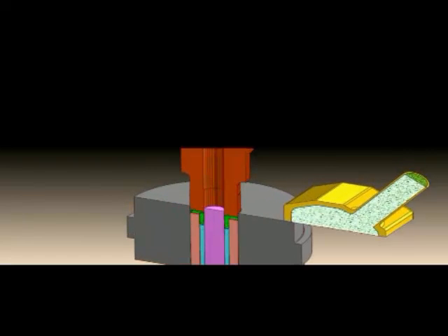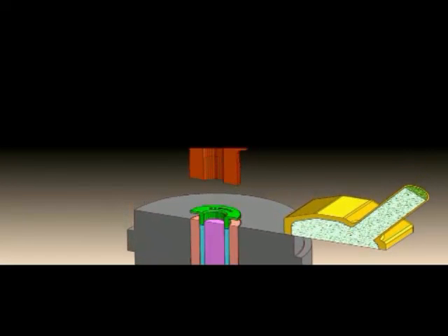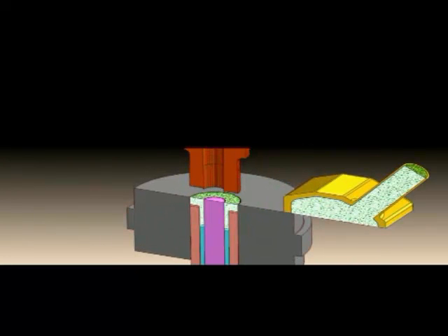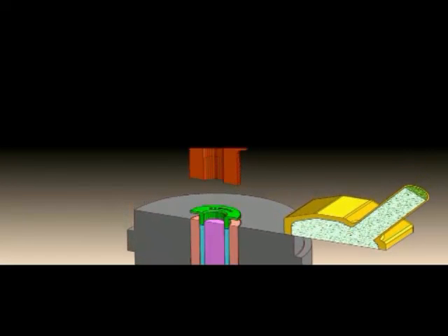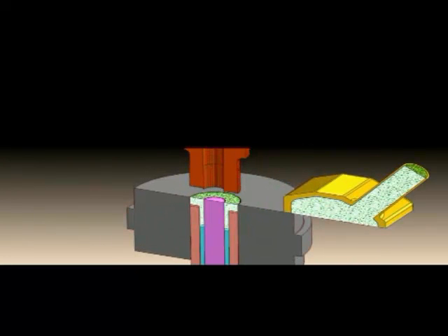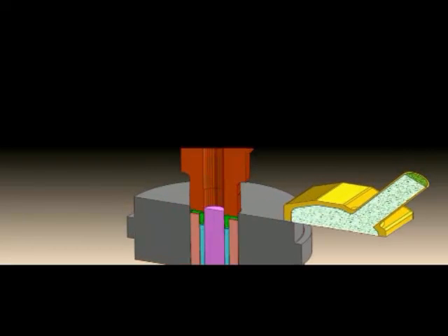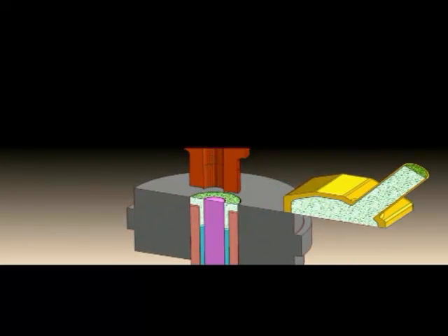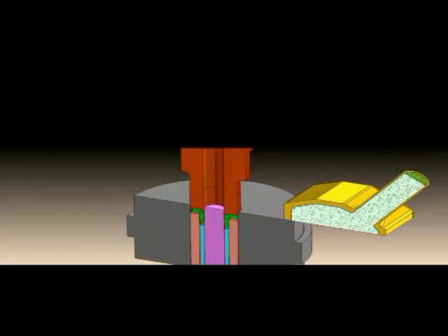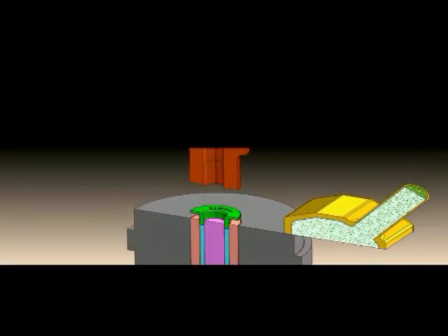It's also a quick note that the tooling we use is primarily a carbide type die, maybe a carbide pin, and very tough tool steel punches. So it's not uncommon to get generally 300,000 or more parts from every tool member. However, it is Symmco's responsibility to maintain those tools for the life of the project. Essentially, in the powder metal tooling, once you've created that tooling to meet your initial specific needs, we must maintain that tool for the life of your project.